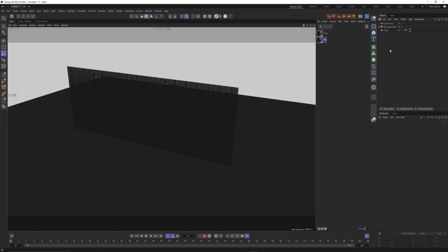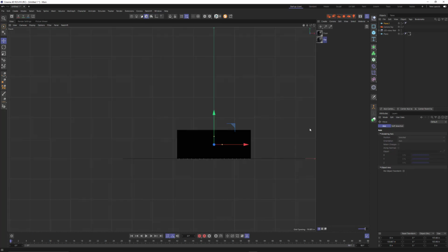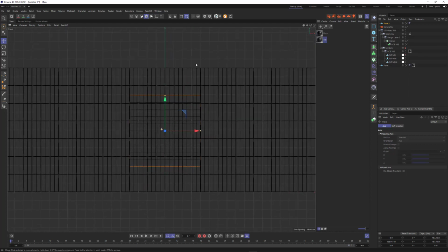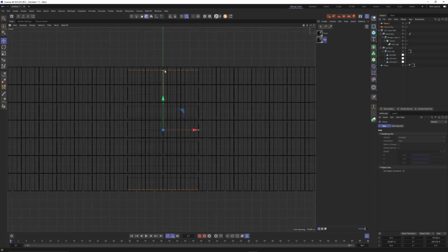We're going to take this, make a plane, and set this to, how about -Z? That's good. All right, so we're going to get this into the right orientation. Here, let's go to a front view. And once again, I want to just turn off these crossbars here so I can see what I'm doing.